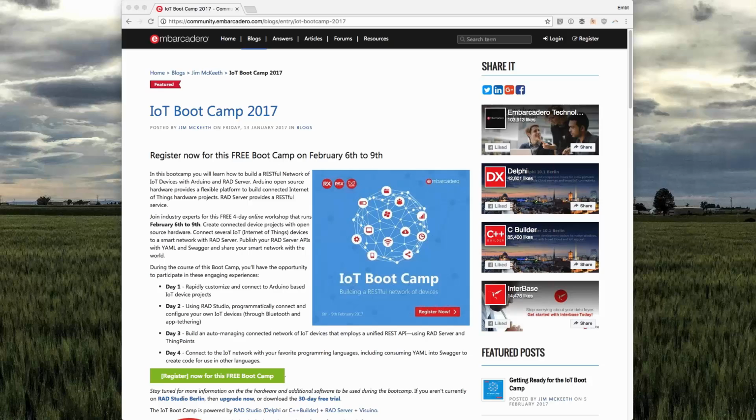But on the other hand, this is compiled code. So on one side it's compiled code, on the other side it's a microcontroller. Even if you don't get hold of the code of the microcontroller, you probably can reverse engineer the logic of the code, just by measuring what happens on different pins for most parts, unless you're running some really complex filter inside or something. On the other hand, even if you extract the assembly code, it will be as complex as reverse engineering assembly code.